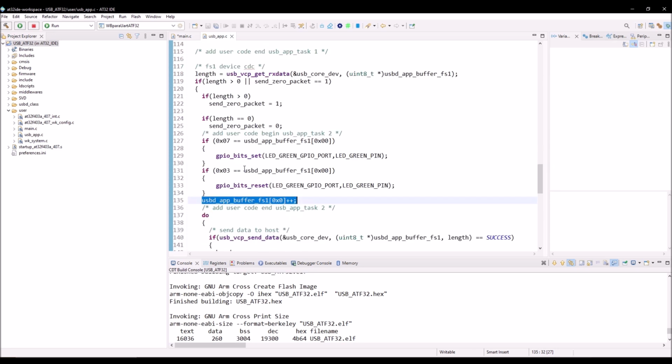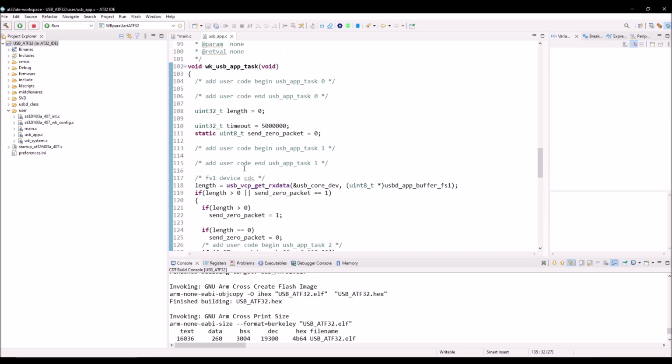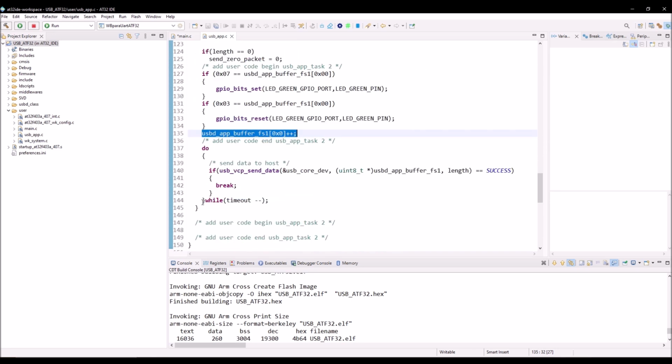It can be seen that the transmission process is synchronous or blocking, as it remains in a loop for a certain period, waiting in case the transmission process is not completed. I was considering creating my own task based on state machines and asynchronous delays, but my goal is only to demonstrate the functionality of the USB module.